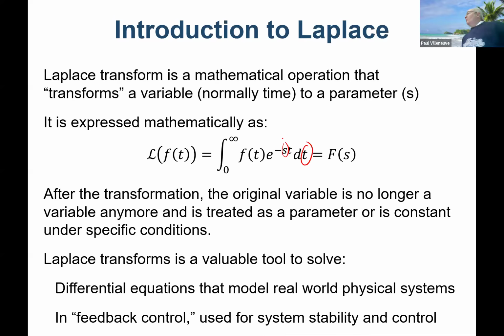But we actually need the math to really truly understand what's happening. A PI or PID controller is actually doing math internally, right? It's proportional, integral, and derivative, right? Those are differentials there to be able to actively control a system. And so if we want to use feedback control effectively, we've got to be able to understand Laplace.